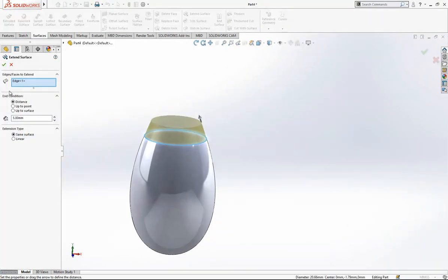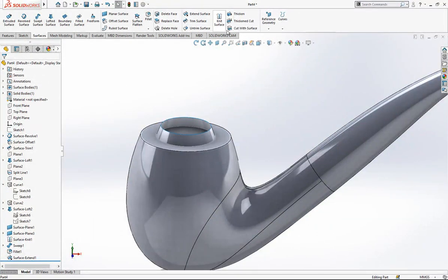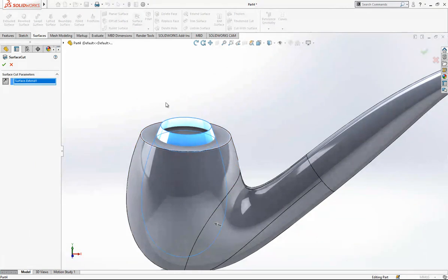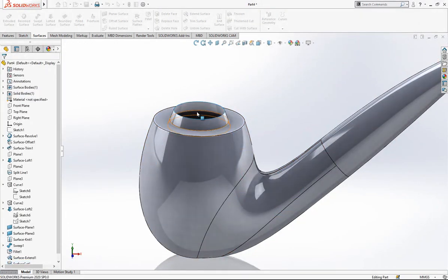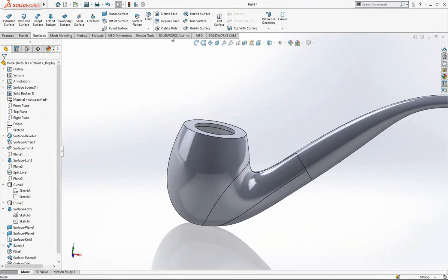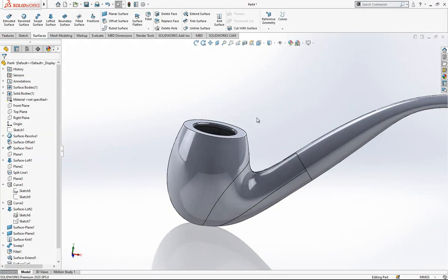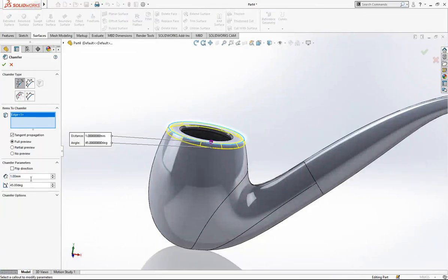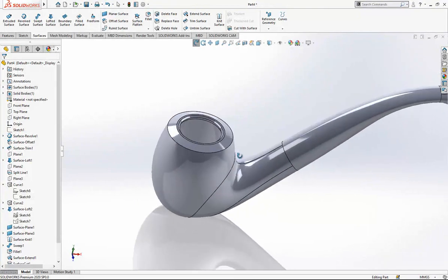Then we will make an extend, show the solid body, and now we can cut with this surface. This command works like a cup. The volume should be fully closed to be able to cut, because it was inside and it wouldn't cut like how I want. That's the reason I made the extension. Now this part also looks nice. Here a millimeter chamfer, and outwards I will add a 3.5 with 20-degree angle. This is good.